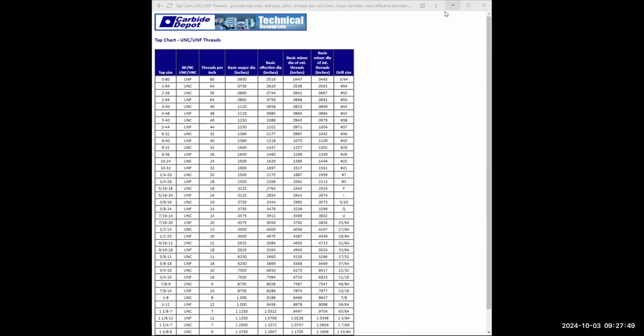Now, what I want you to do is we need to start putting some dimensions on here. So we're going to go to this tool right here. It says linear. Select linear and look, click here and here. And that's way too many decimal places. I'm okay with the size of the arrows. I'm okay with the size of the text, but way too many decimal places.